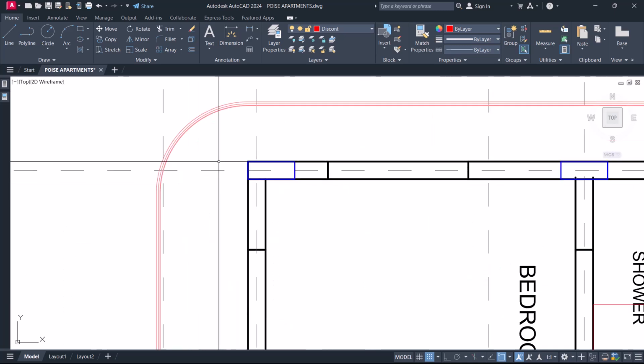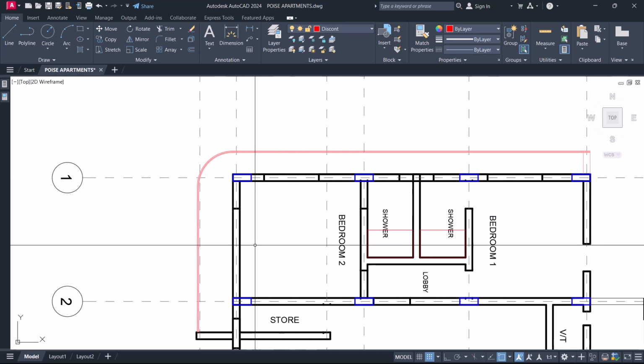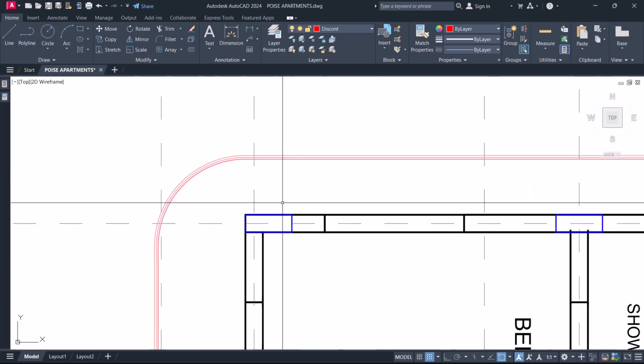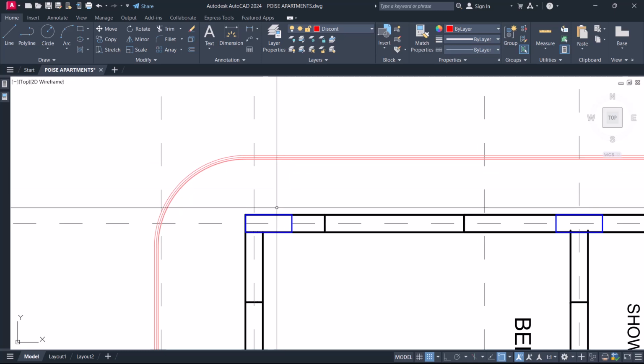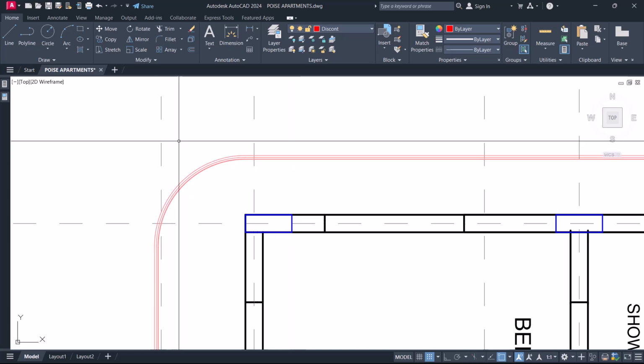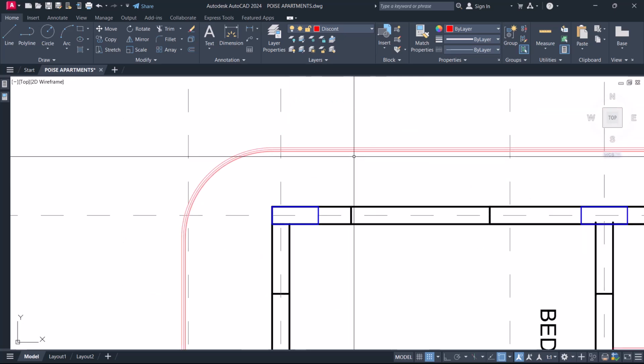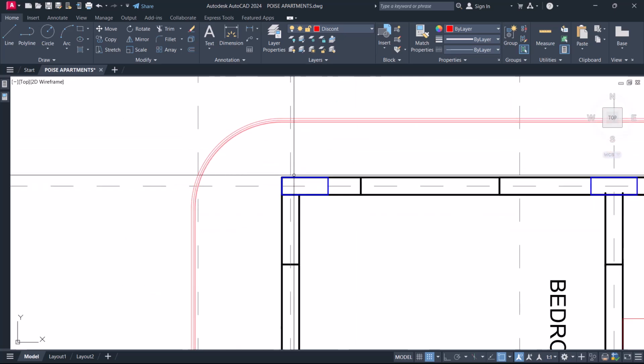So any opportunity we see to have columns at the center of our slab will be even more appreciated. In other cases of design, we are always trying to avoid cantilevers or extras coming out of our slabs, coming out of our column areas rather. But in the case of flat slab design, this is actually advantageous. And like I said, this is more reason why when you see a lot of flat slabs being constructed, there are always extra areas from the column points.